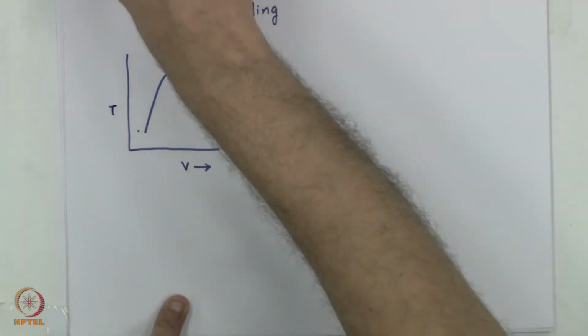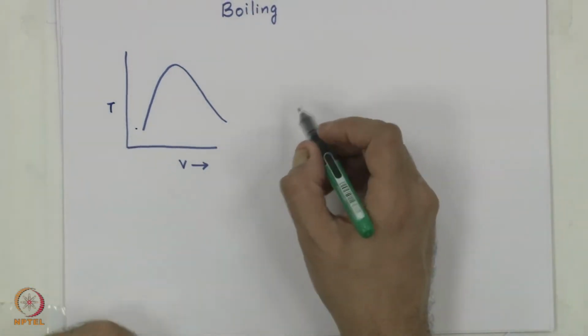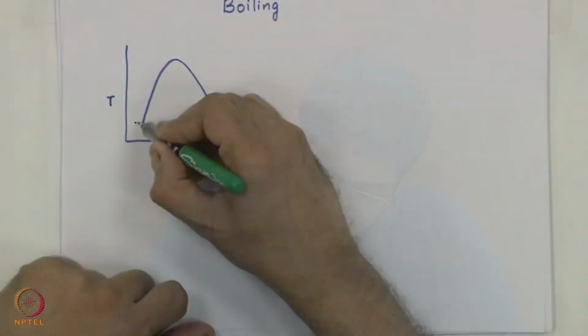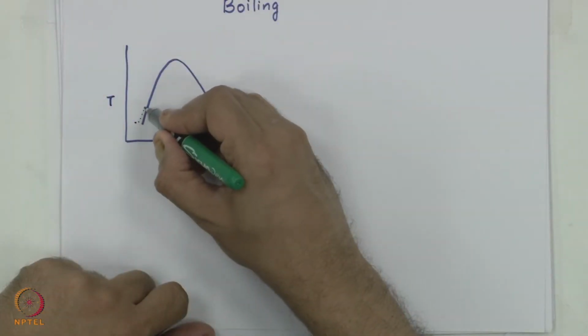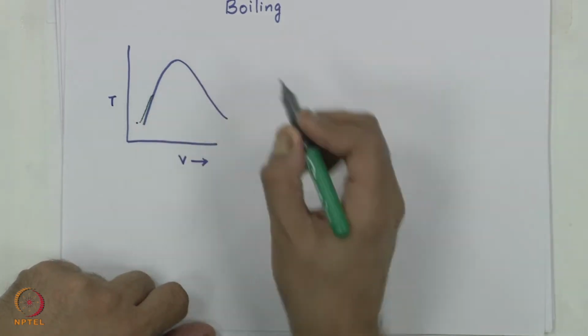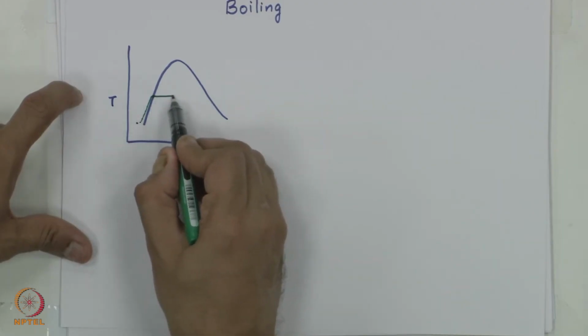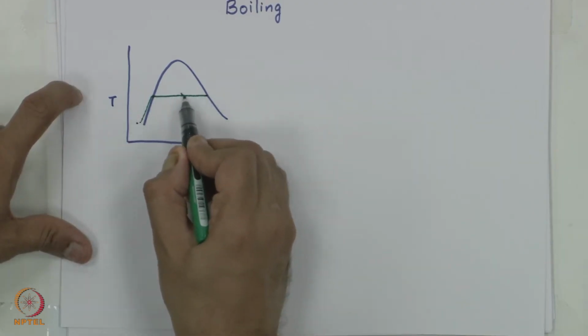And what happens in a TV diagram is essentially you have a thought experiment which was done where you had a certain mass of water whose temperature was kept at 30 degrees. Progressively heat was added and the pressure maintained constant, and you would see how the specific volume increases progressively until the temperature became the saturation temperature. At saturation temperature, if you added more heat, this would happen.